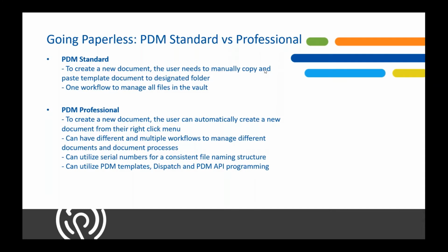So let's take a look at the differences between PDM Standard versus Professional. In PDM Standard, in order to create a new document, you would have to have a template file somewhere in your vault that allows your user to basically copy that file and paste it to whatever folder they need it to be in.